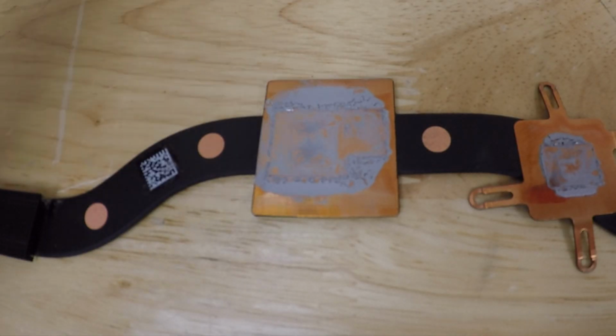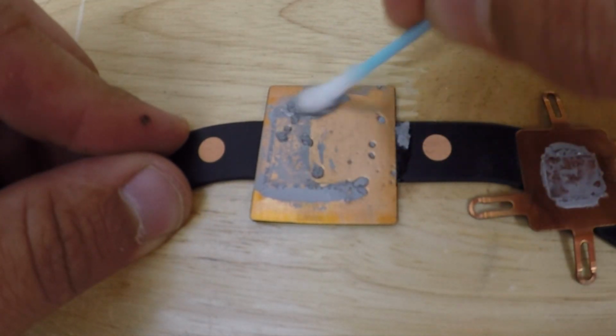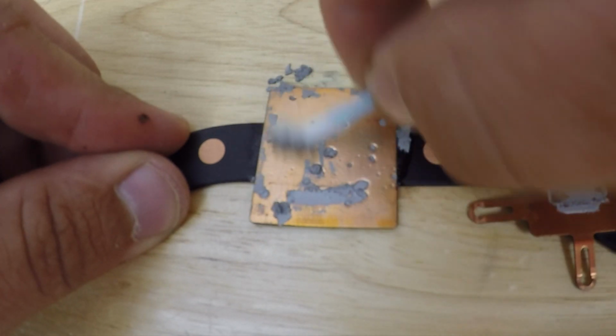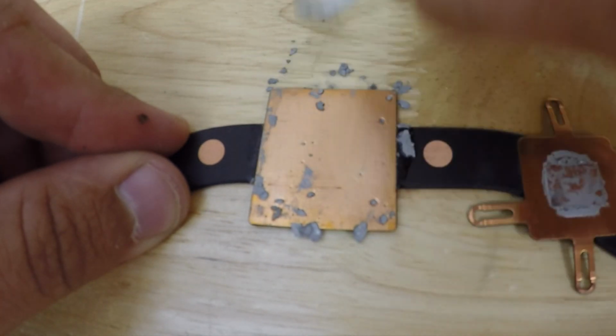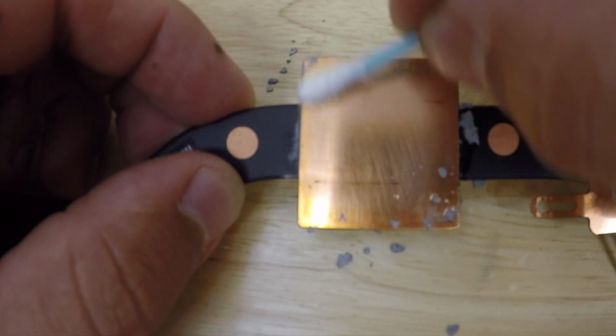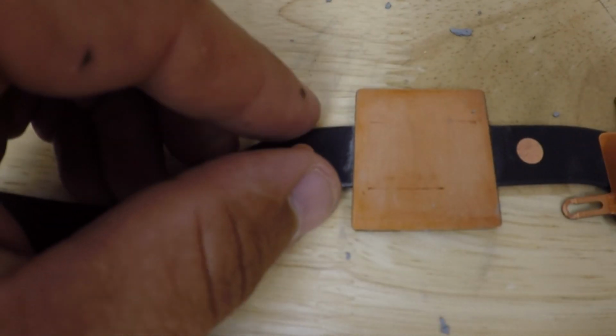Next, you're going to want to take the heatsink and clean off the copper plate for both the CPU and the GPU. You're going to take 90% isopropyl alcohol and a Q-tip, and scrub off the surface of the copper plate. Now you can see that the thermal compound that was on the MacBook Pro is very dry. I think this is the main reason why I was having high temperatures, because it wasn't doing an adequate job of transferring the heat off the CPU and GPU to the copper plate